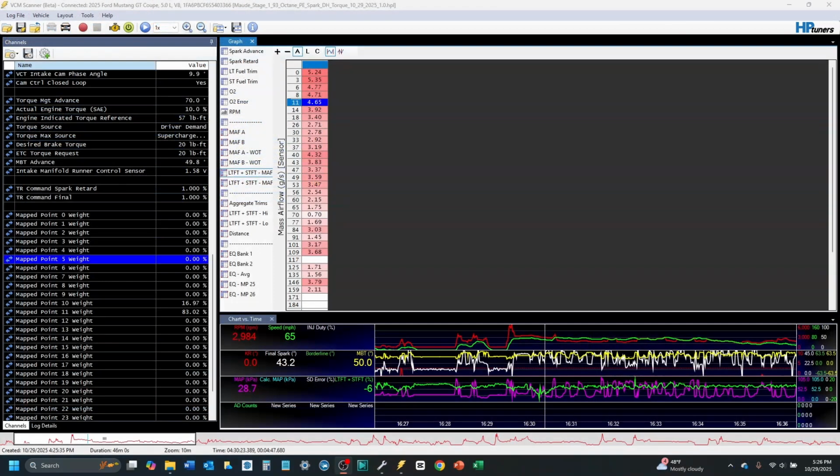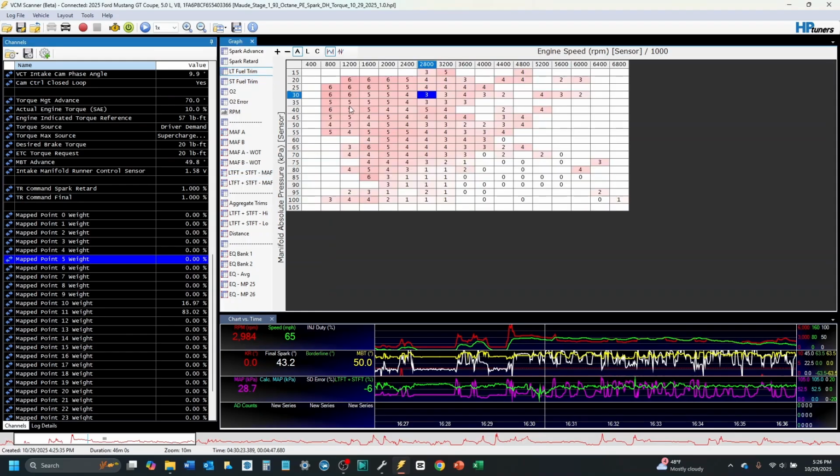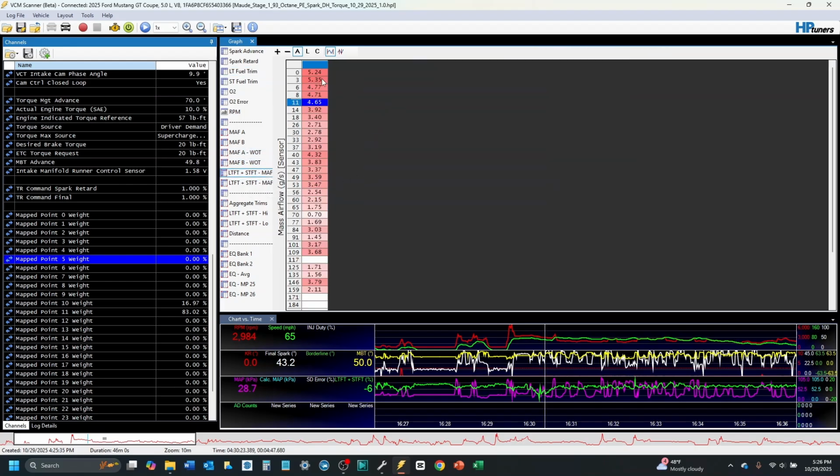And so now when I look at the mass airflow, I'm still looking at trims matched against airflow breakpoints. And it's not a surprise to see, here it's breaking it out by pressure and RPM. Here it's looking at the mass airflow sensor itself. And look, the trims here again on the bottom are kind of lean. We're going to touch those. Up top, it looks like the modeling we did over the summer is still holding up pretty well. I'm not going to complain about that.